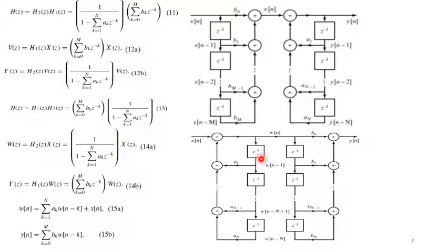So that means we are using redundant delay units, because if we look at this one, we have the signal with value w[n minus 2], and again here w[n minus 2]. Similarly, if we assume the order of both systems is the same, then again here we have a delay of w[n minus N], and again here. So that means we are using redundant delay units, and we can simplify them.